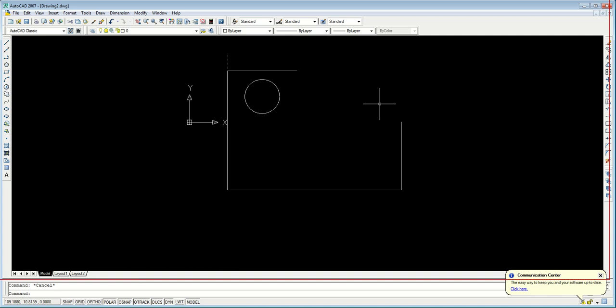Usually if I give you a drawing, I don't specify the dimension or the angle of the inclined line. If anybody gives it to you, it's okay, but usually we don't. We give the dimension that is vertical or horizontal, for example for this line and for this line. And you see that there is an inclined line between this point and this point, but I don't know what the angle is. That is okay, we don't have to know the angle.